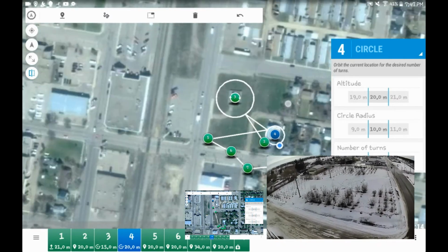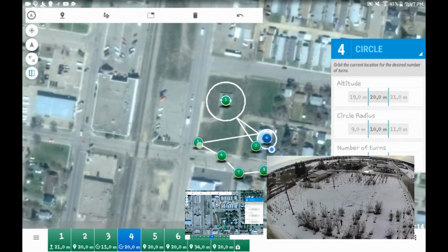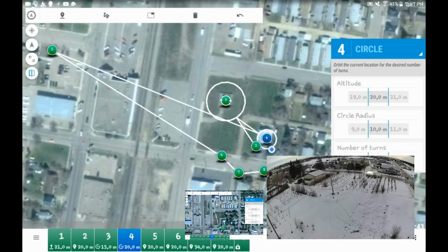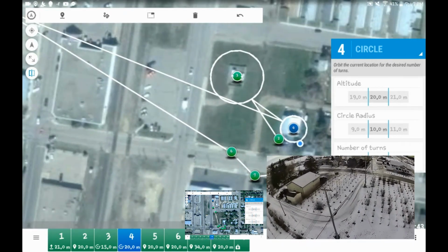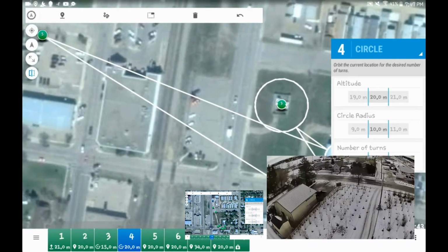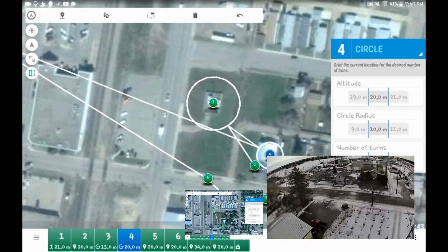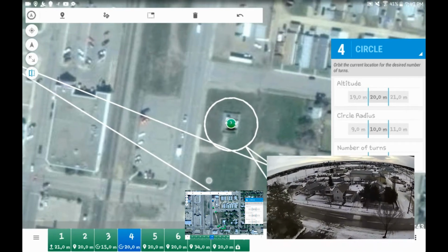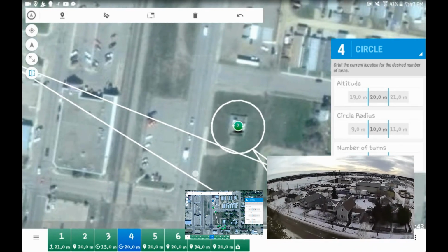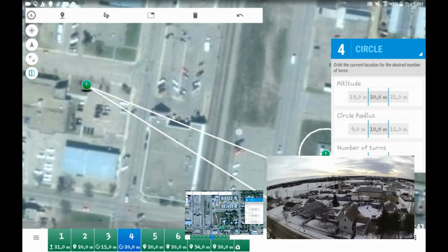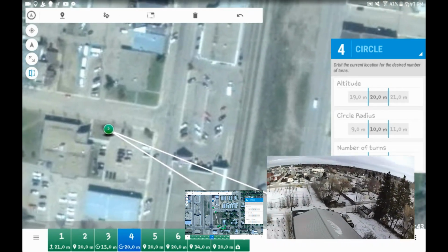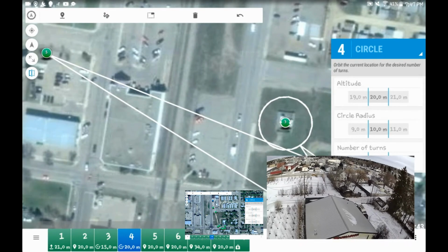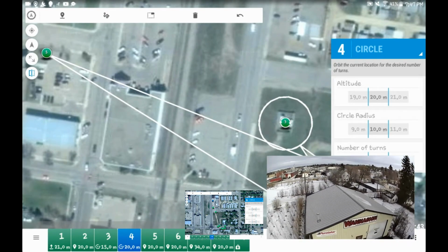So let's say, for example, you took waypoint 5 and you flew it way over here. Now you're not going to be able to see that way over there starting from our building, and it's going to lose signal. So as your mission happens, it's going to take off, fly to 2, do the circle, go to the look at the circle on the little building there, and then it's going to fly way over there. Now say about here is where you're going to lose your signal. As soon as it loses signal, the drone is programmed to return to launch. It overrides the auto, it aborts the mission, and it returns to launch.